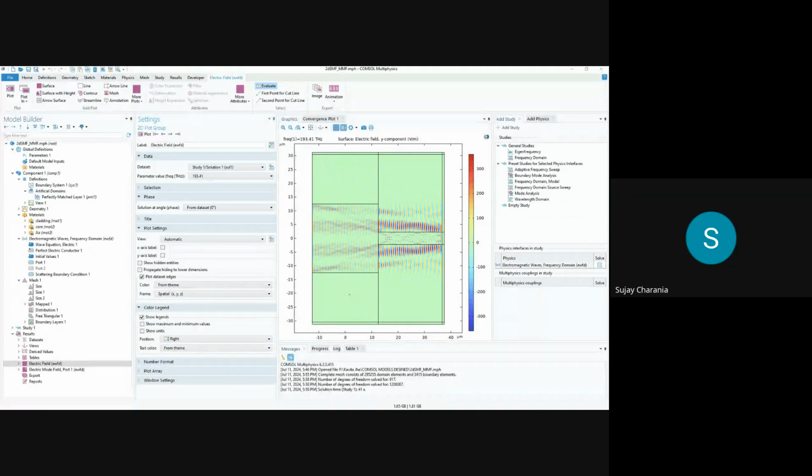But the follow-up question: is it then possible to know whether at least the higher energy mode or fundamental mode from the multi-mode fiber is actually propagating, and how much percentage of it is going to the single mode? Because if the main energy mode is lost, then it would be really difficult to get the data out in the single mode.